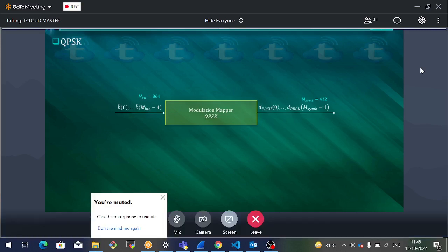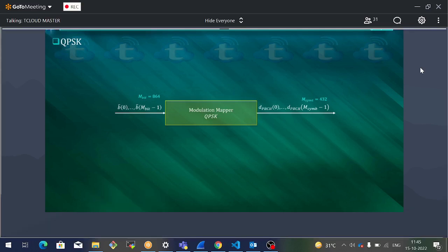On the receiving end, first of all, the receiver can decode this PBCH only after decoding PBCH DMRS. But assuming that the PBCH DMRS is already decoded, the mobile can easily decode PBCH, because that is the only linking point. In the scrambling, we have used those bits that are learned from the PBCH DMRS.